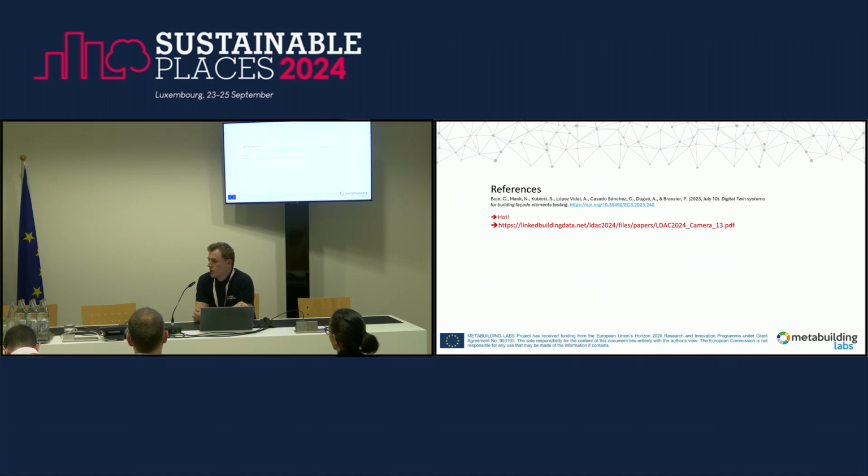And then we've also experienced in previous projects where we have a lot of data that is changing in graph databases, to do SPARQL to delete something and to update and create all the dependencies around it is quite difficult. When you just have your BIM model and you export to a graph and then you use that as a static component, let's say, that works just fine. But as soon as you're dealing with IFC tasks, for instance, for scheduling, and you start putting a task in and deleting it or modifying it because, with scheduling, time moves on and objects disappear or stay redundant, you might end up by the end of the year with 1,000 tasks which you have to query and they all come in together, and so it's becoming slow.